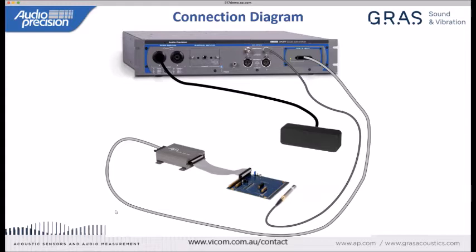I will say that this picture's depiction is a little incorrect. I actually have the 1/4-inch pressure field microphone at 90 degrees to the sound source. A little advantageous detail: at a 1/4-inch size, a free field and a pressure field microphone have a flat frequency response to 10 kilohertz.